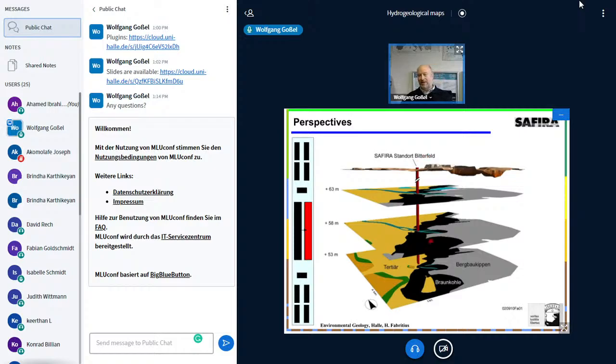But as soon as the pumping in this area stops, and the water levels go up, perhaps leading to completely different path line directions, then you perhaps get clean water. This channel is only very small, so there is only a short time after stopping the pumps and changing the flow directions where you get the high contamination. And your remediation plant is then at completely the wrong site, and you have the completely wrong method to remediate your contamination.